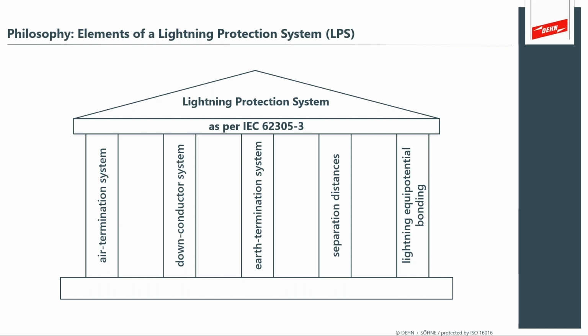The point being that two pieces of steel that are on or around the lightning will experience different voltages if they're not bonded together. And if there are different voltages, you have now invited lightning into your structure. Those different voltages will now play havoc.